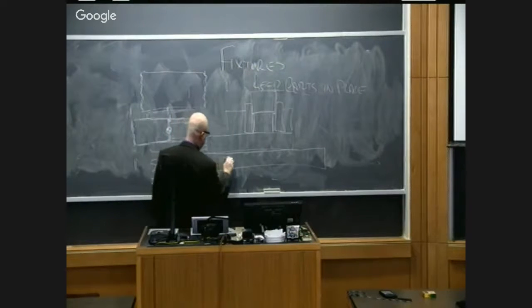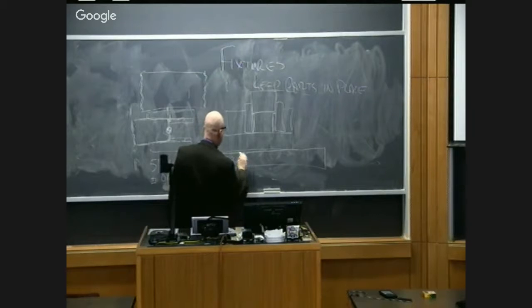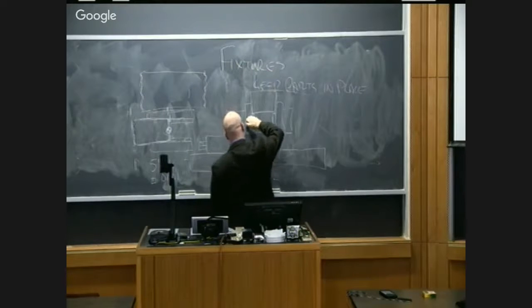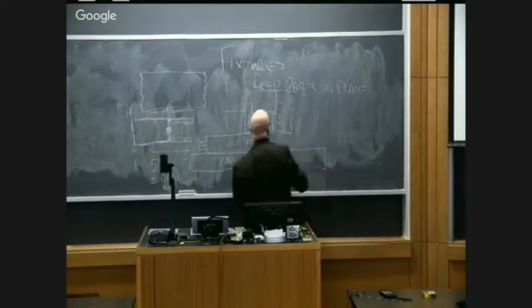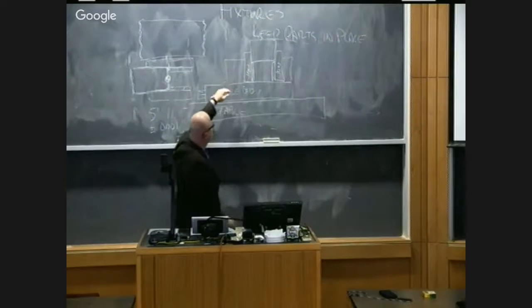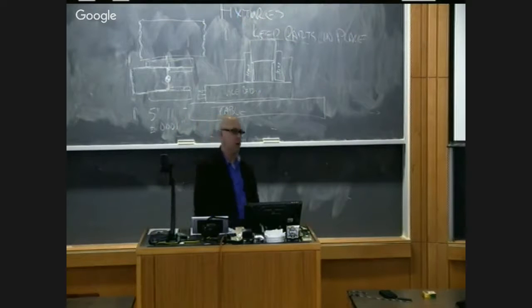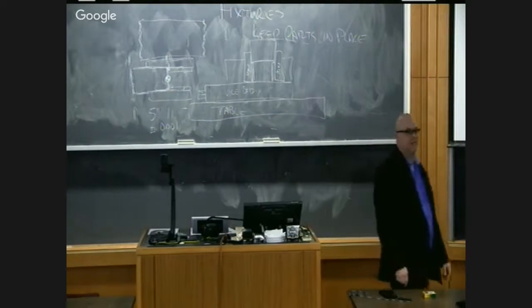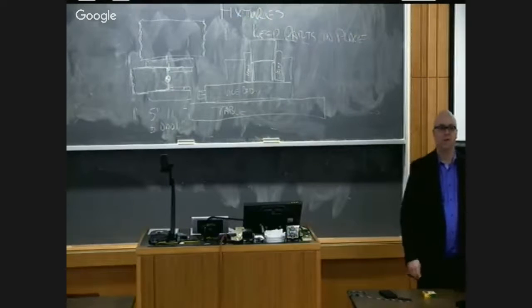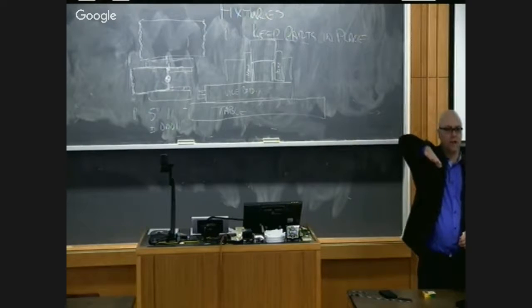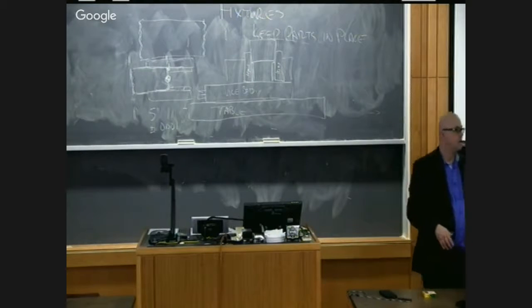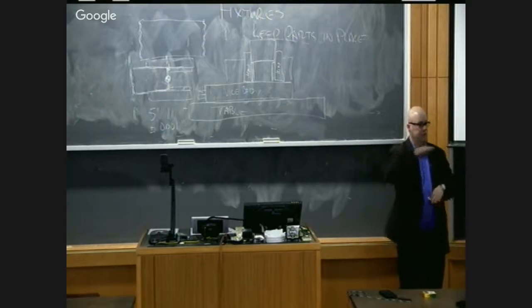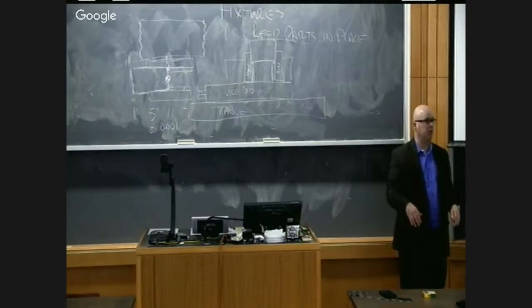So this is the table. Vise body. Right? And so our parallels, how could that go wrong? What's going to happen if our part's not flat, not parallel? If we machine the Z-surface, the top and the bottom won't be parallel to each other anymore.